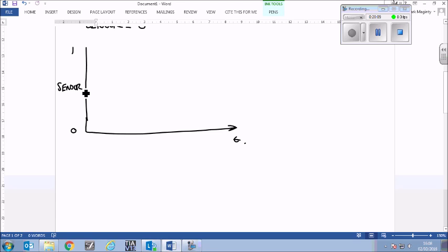So when you first turn on the system, the sensor, this IP4, which is the diffuse sensor, is on the whole time, because it's wired normally closed, remember that? So when there's nothing in front of it, it's on effectively. And then if the car moves forward and the front bumper touches it here, at this point, it goes to the off state here. So this here is stage 1, and I write it over here.